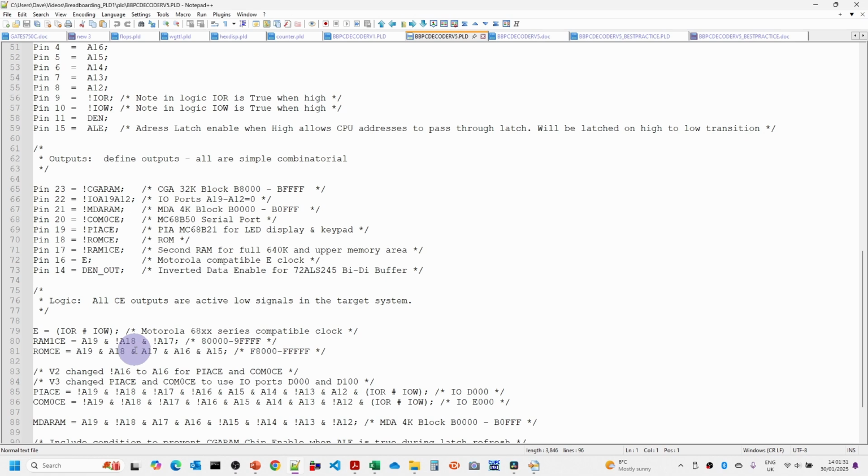And then when we're actually defining the rules here, all I've been doing is doing the chip enables using sort of hard-coded rules. Generally, if an address line is true, then it will have just it straight there. If you've got an address line with a not on it, then it basically means that will be 0 for the conditions that we're dealing with here. And because we've defined the enables here as active low, we only ever have to worry about dealing with true positive outcomes from these things.